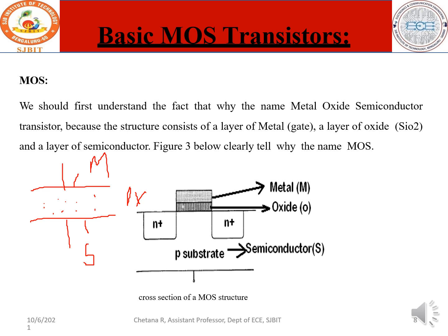So this is how we see the cross section, and the counterpart of this is your MOS structure, but still I can conclude by saying that this is your NMOS device. As I have already told you, you have to have a substrate, right? So substrate is the basic material. Here you have P substrate. So right now let me take it as N substrate. So this is of N type, and I have to appropriately find out the diffusion area. So this becomes your P type, and above this you have your oxide.